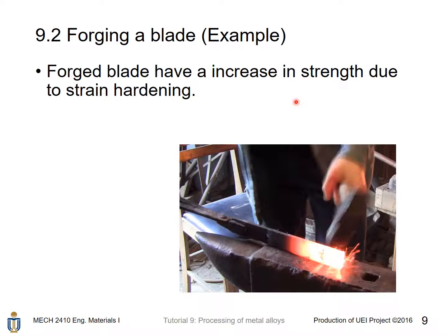within a workpiece just after casting, because all those grains are newly formed after the casting process. That is the reason the cast blade will have a lower strength compared to the forged blade, and that is why we use forging to make a strong blade.